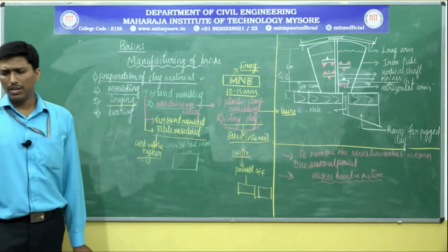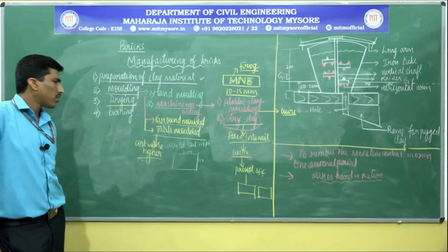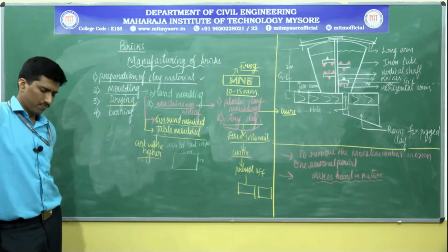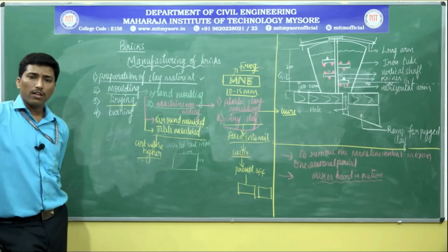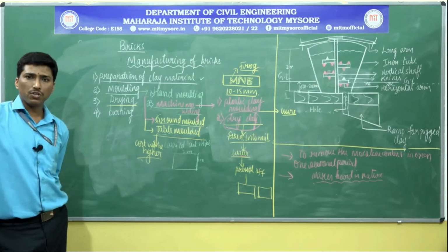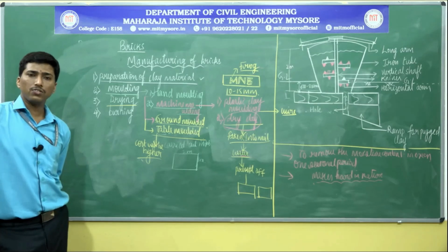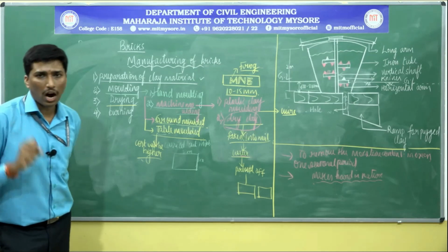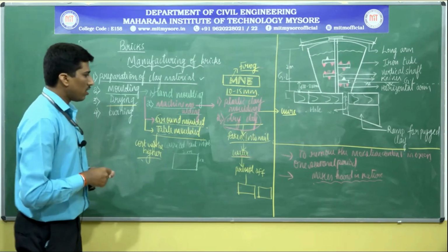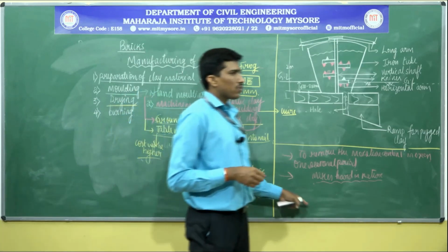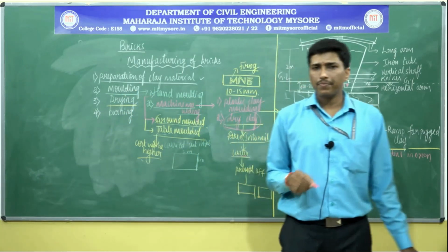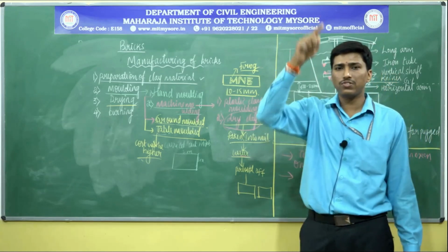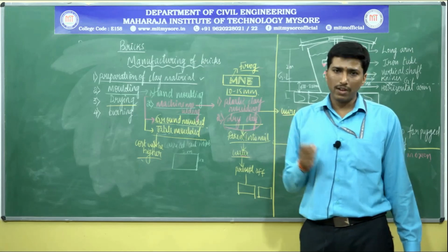What is the burning process mainly? It is the process of subjecting the bricks to higher temperature, where the ingredients or compounds are fused together, making the bricks very hard in nature. Here, if you see the conditions allocated for the drying of the bricks, they have been stacked in a longitudinal as well as cross manner.